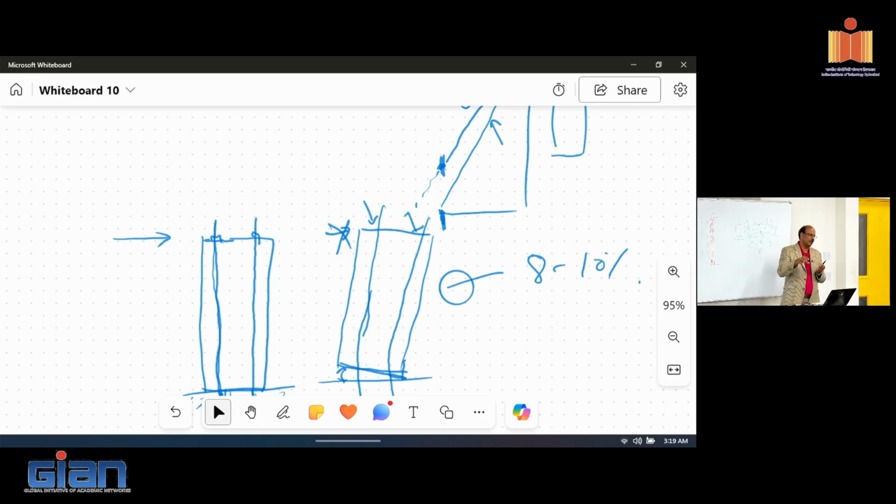We were able to calculate that amount of damping. That's in the 3-4% as well. So rocking, you say? Yeah, just on the rocking itself. Okay. So we've done that. We have also done it where we put a rubber interface. It increases the damping. So instead of rocking on top of concrete, there's a high damping rubber or something different at the interface. So you let it rock, you're moving it by 1-2%.